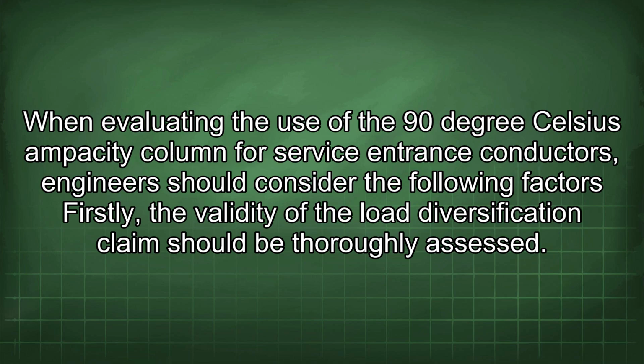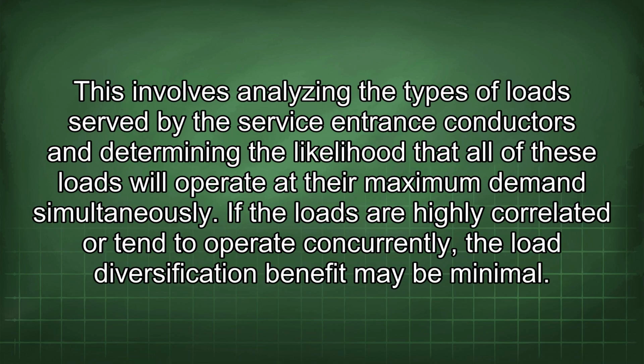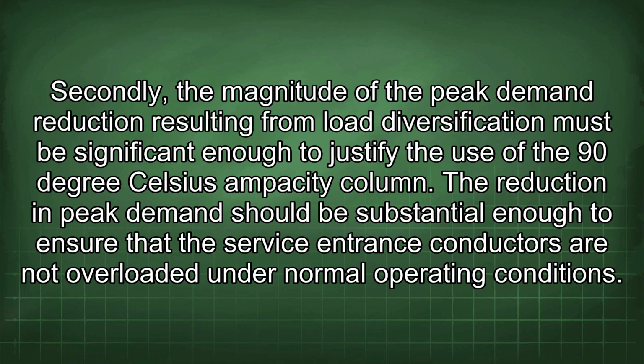Firstly, the validity of the load diversification claim should be thoroughly assessed. This involves analyzing the types of loads served by the service entrance conductors and determining the likelihood that all of these loads will operate at their maximum demand simultaneously. If the loads are highly correlated or tend to operate concurrently, the load diversification benefit may be minimal. Secondly, the magnitude of the peak demand reduction resulting from load diversification must be significant enough to justify the use of the 90°C ampacity column. The reduction in peak demand should be substantial enough to ensure that the service entrance conductors are not overloaded under